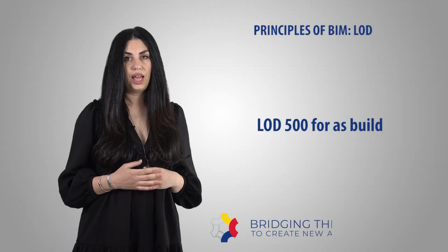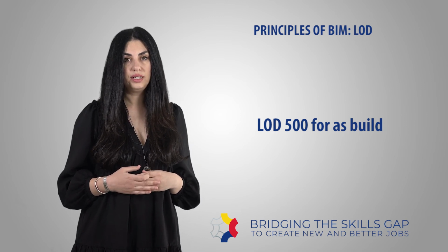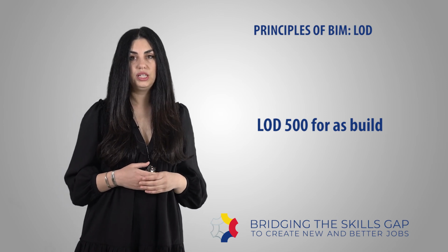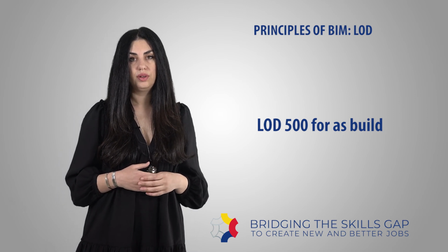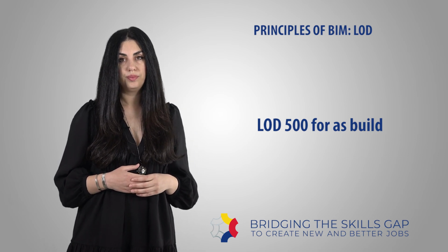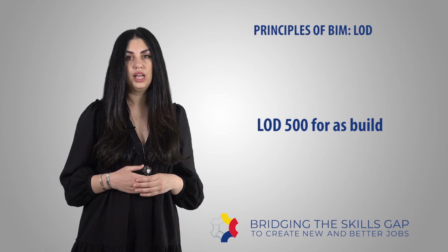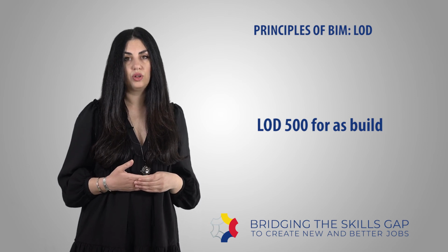LOD 500, as built. Elements are modeled as constructed assemblies for maintenance and operations. The model element is a field-verified representation in terms of size, shape, location, quantity, and orientation. Non-graphic information may also be attached to the model elements. Basically, LOD 500 relates to field verification and is not an indication of progression to a higher level of model element geometry or non-graphic information. It is simply an as-built model.